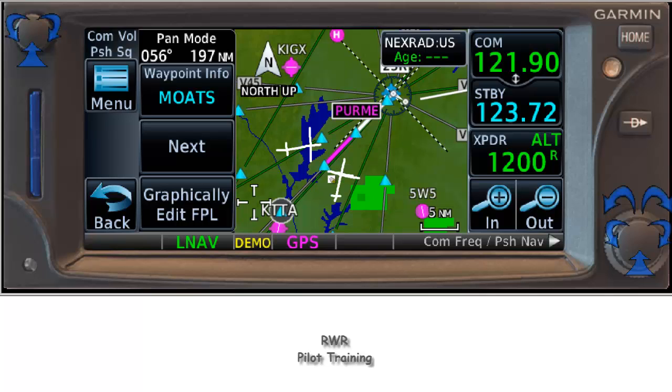Keep in mind that since it's an ILS, this is really an exercise in position awareness and has nothing to do with what the airplane will do once it's operating on the localizer. For now, we're still in GPS mode, and so whatever we activate or do here is what the airplane is going to do. So if we're going to activate a leg, we have to have heard the H word, heading, so that the airplane is actually tracking the way the ATC wants us to.